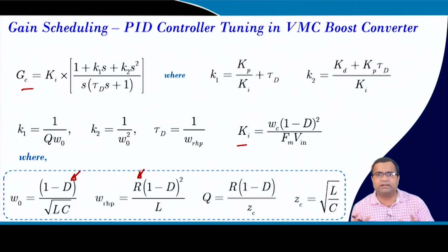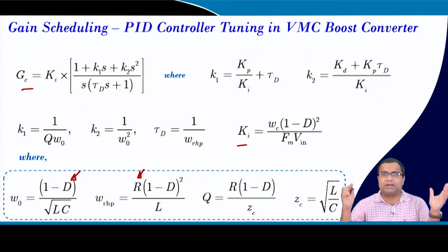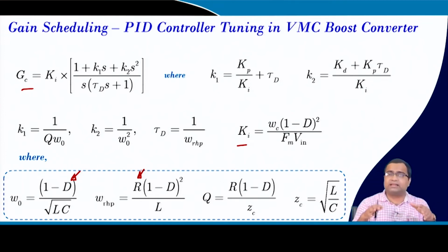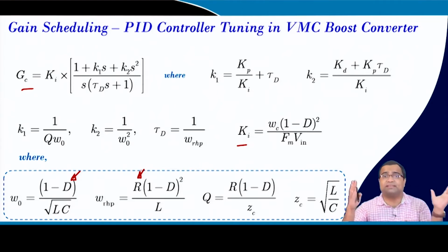That means where you are fixing the compensator gain at the very beginning in analog control, where we do not have flexibility to change the controller value abruptly, because they are implemented in the off chip or outside using actual components, where changing resistance, capacitance, and all these values are really difficult. But once you plug into digital, where the coefficient is just a number, that can be updated by this method. So, this method can improve performance over the worst case design where the controller gains are fixed in analog control.